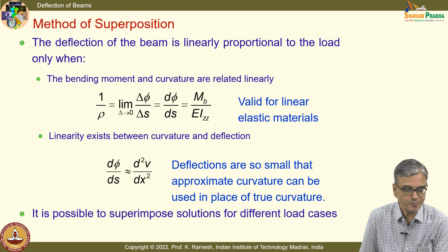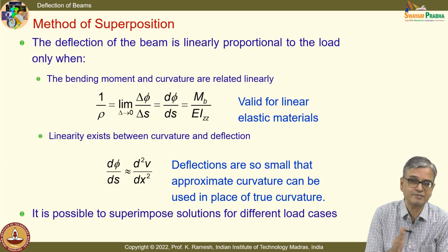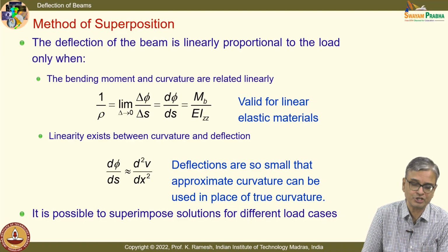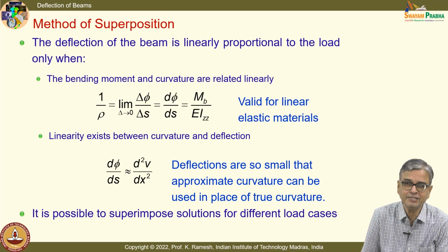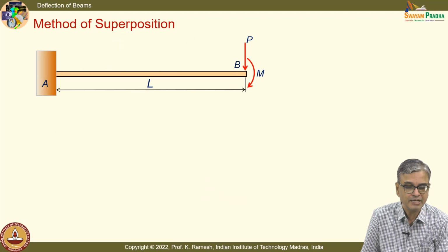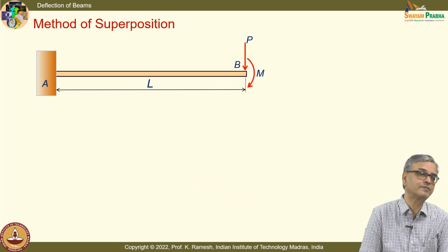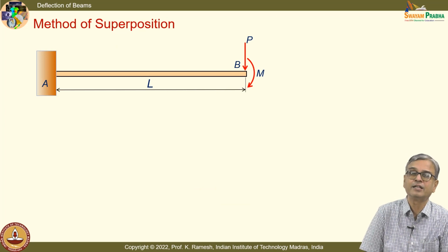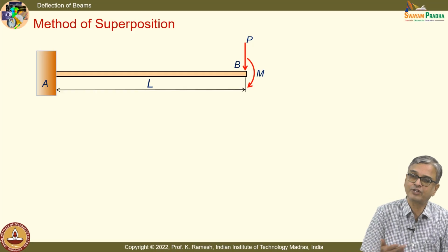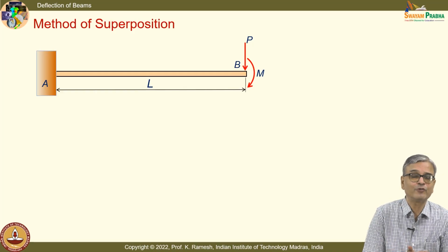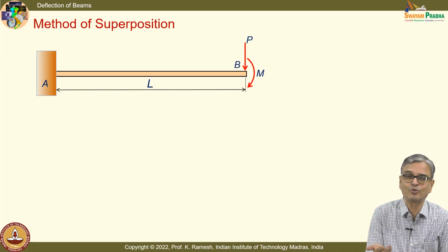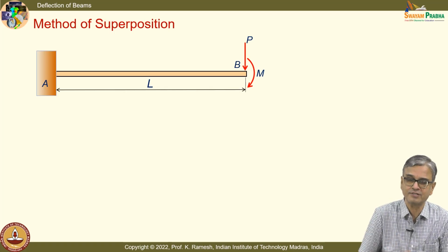It is possible to superimpose solutions for different load cases. So, you should know what the limitations are. You can't have large deformation and use the principle of superposition. Small deformation, you can do it. And I would appreciate that you try to do this problem as homework. We already have the solution for end load and the solution for the bending moment. Even before you start the problem, you know what the solution is. Okay, it is a linear superposition of these two results.